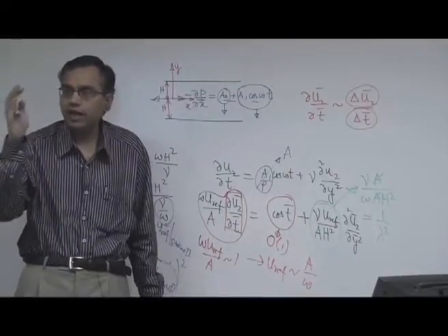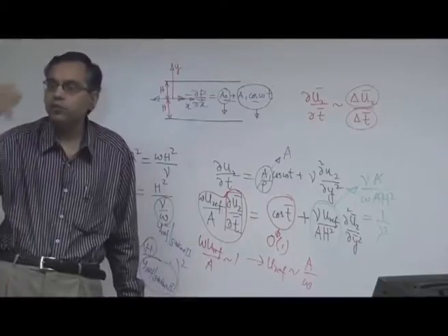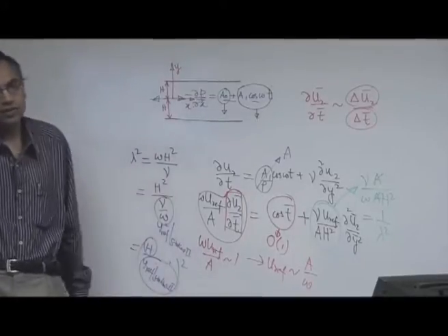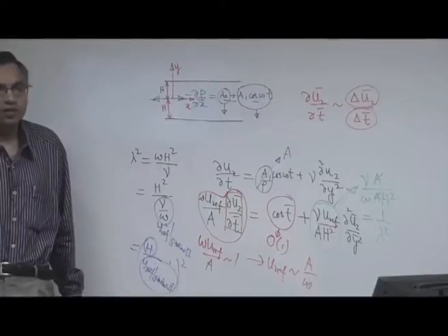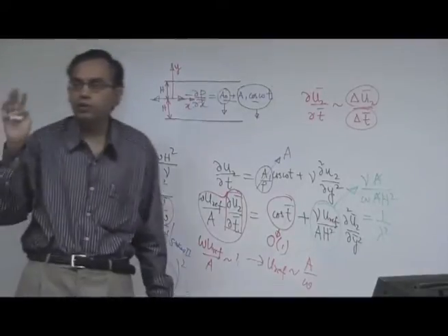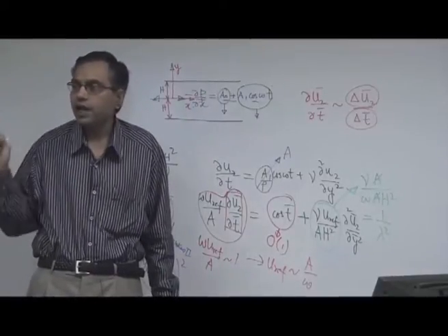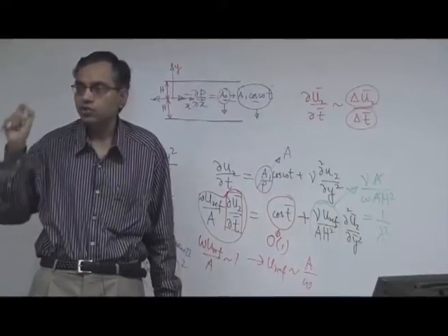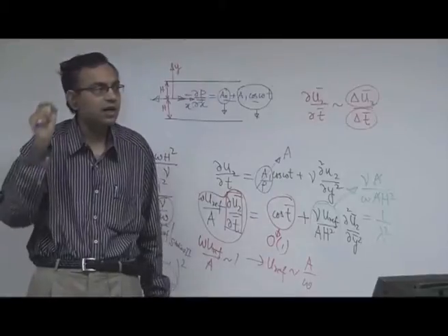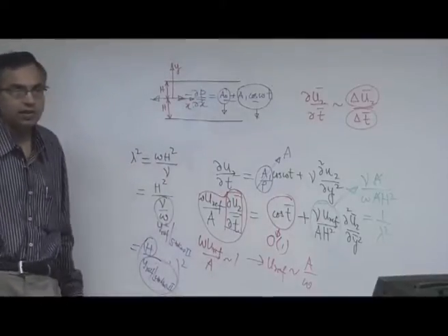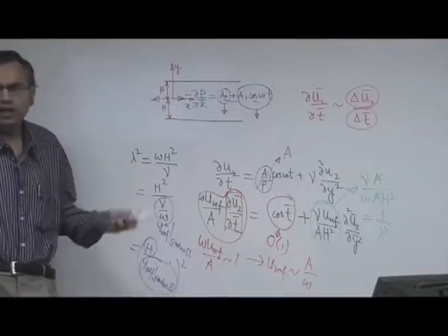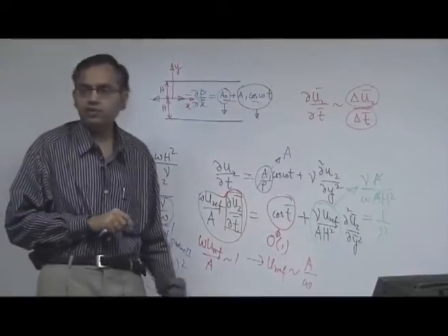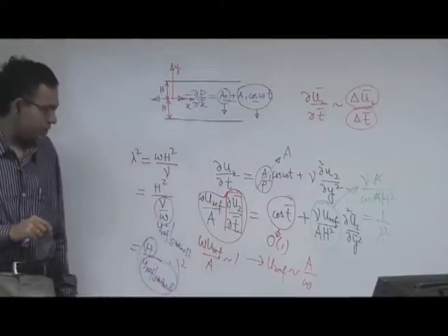Even if you take the kinematic viscosity, let us say that the fluid is water. So, say that that property is fixed. So, mu is roughly 10 to the power minus 3 Pascal second and rho is 10 to the power 3 kg per meter cube. So, kinematic viscosity is roughly 10 to the power minus 6 meter square per second. That is a rough calculation for the kinematic viscosity of water.